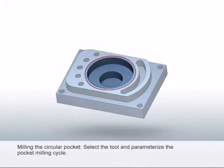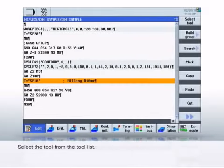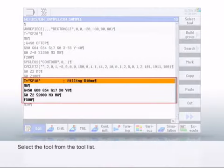As the next step, mill the two circular pockets. To do this, use the special pocket milling cycle. First, select a tool from the tool list. A shaft milling cutter with diameter 10 is used.